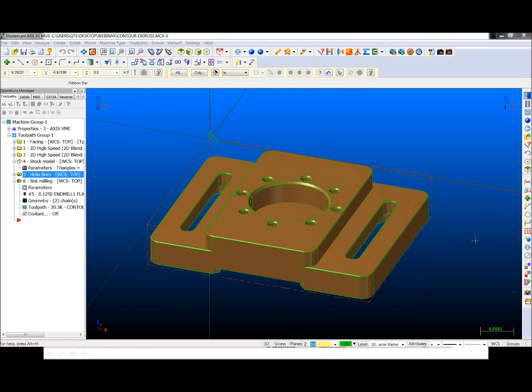Now moving on to the thread milling toolpath. The thread milling operation takes a single tooth or multi-tooth paddle type tool and does helical interpolation with the machine tool on a mill, creating threads. Very popular if you have large diameter holes that have coarse threads. Tapping is not an option here. We thread mill, and people are using thread milling for multiple sizes. You can adjust the hole size based upon cutter comp. Okay.